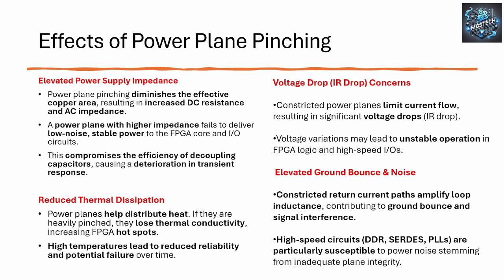It's an impedance, so they're proportional. The other thing to think about is if you're cutting copper out from underneath a part that may get hot, then you could raise the temperature of that part, and that might be a consideration for you.